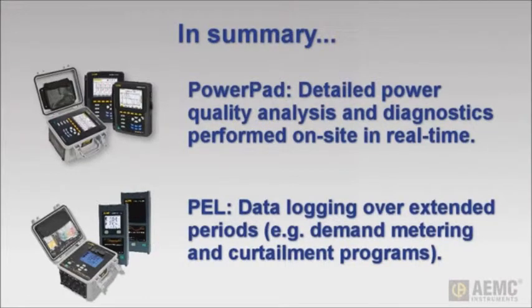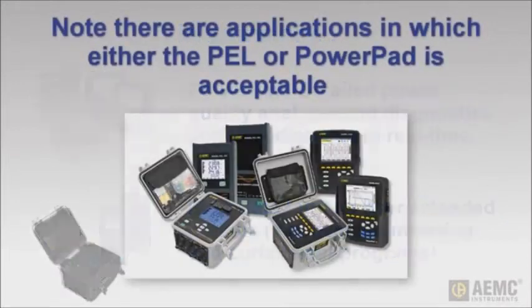The PEL, on the other hand, is ideal for recording energy and power quantity measurements and large amounts of data while operating unattended for long durations in environments with limited space and access. A wide range of connectivity options enable you to build global networks of centrally controlled instruments. You can perform long-term data logging and monitoring of trend data, which can then be downloaded to a computer for analysis and troubleshooting. Typical applications for the PEL include demand metering and curtailment programs that often require extended recording sessions.